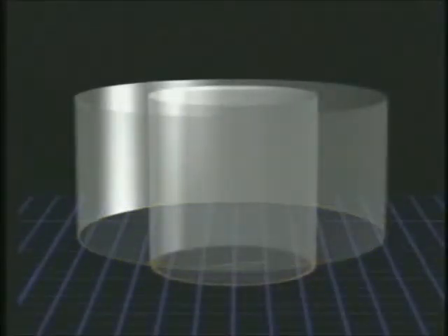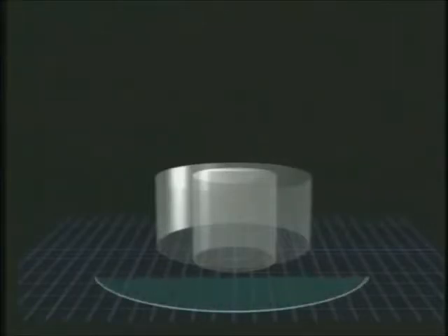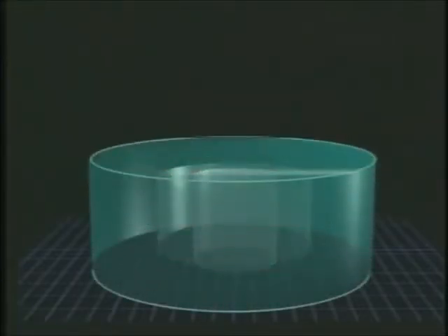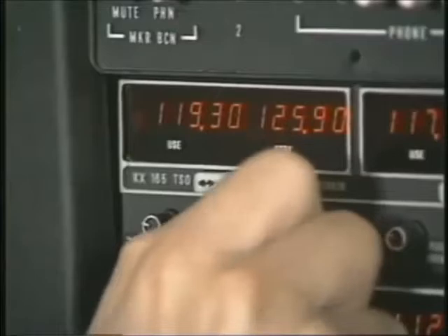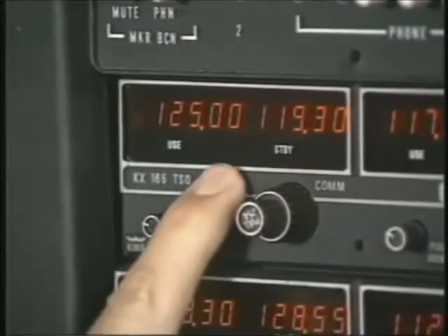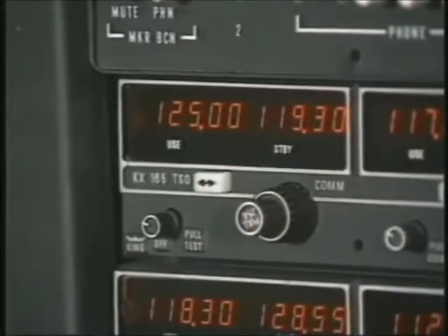If you're approaching an airport in Class C airspace, you must establish two-way radio communications with ATC before entering the outer circle. You are strongly encouraged to make the initial call within the outer area. Let's take a closer look at the procedures for entering Class C airspace. Listen to the ATIS as you approach the 20-mile outer area. Jensen Airport, information Sierra. 1445 Zulu weather, temperature 76, dew point 44, wind 160 at 1.